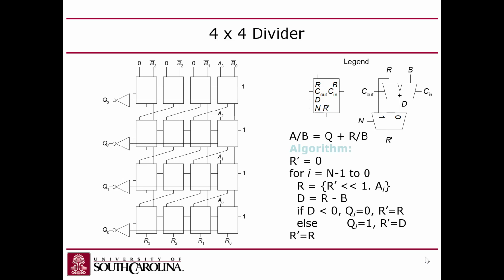Well, a sign bit, right? So would I need to know something from this column? They're showing information from that column. I don't think so. If I add 2 numbers, I'm subtracting 2 numbers, but I'm doing it as an add. I want to know if the result of that is a negative number. You can use the carryout to determine that.